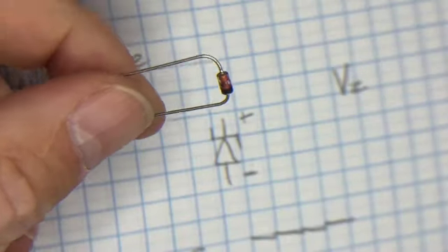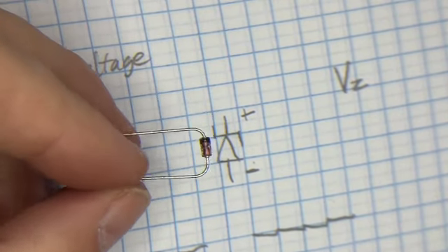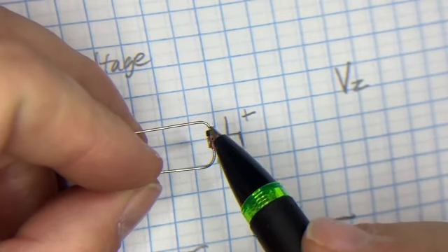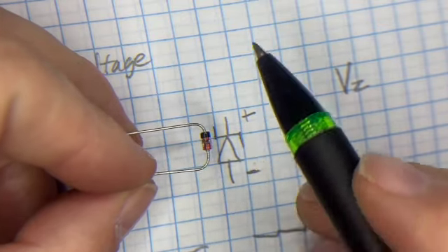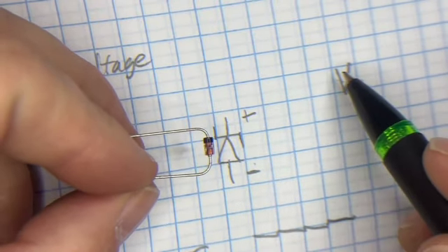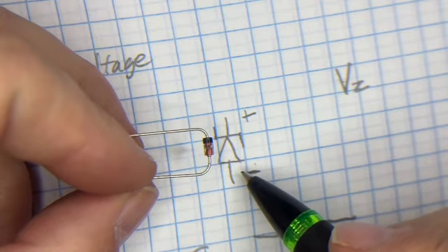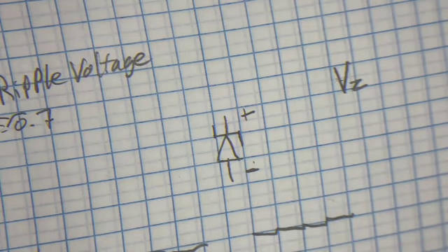And these guys are often used in voltage regulators. See, what happens with these guys is they block the voltage completely, just like any other diode, until you reach this Zener voltage. When you reach this Zener voltage, this guy will start conducting. I believe this is a 15 volt Zener. Let me just run it through my tool here, and I'll get the Zener voltage for you.